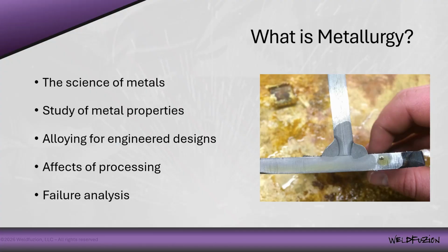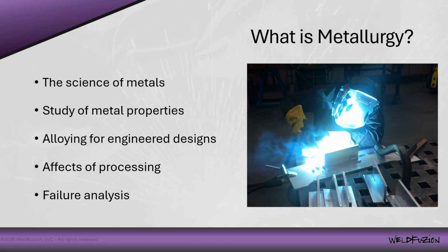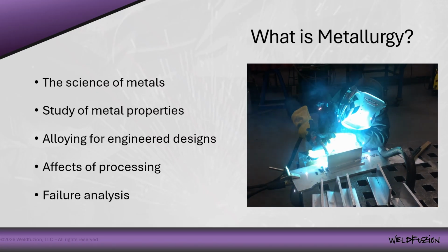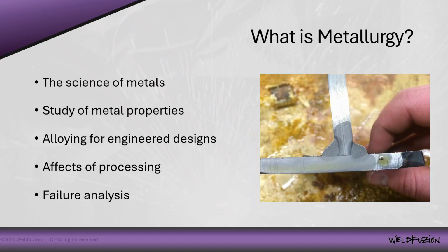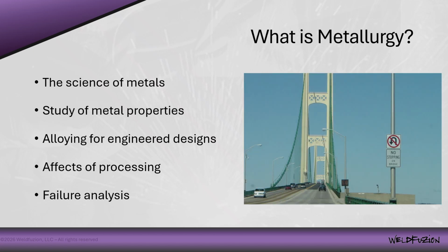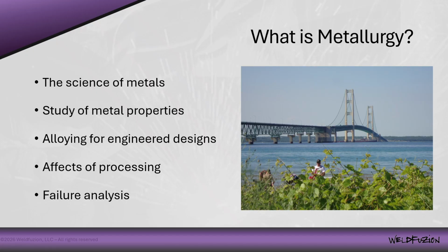Welding heats and melts metals in the same temperature range used to refine and process the material. So the study of metals is extremely important for welding. Metallurgy works to define mechanical, physical, and chemical properties of metals and metal alloys before, during, and after processing. Long-term metallurgy includes fatigue and creep failures that occur after a product or component has been in service for a while, hopefully a long while.